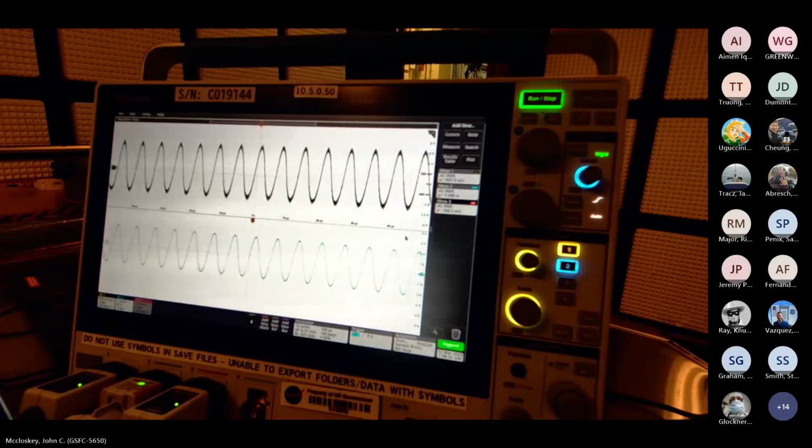If that's how your software works, and it only gives you the option to read a straight up RMS value from your scope, well, then that's what you have to do, but you have to be extra careful because AC coupling can fool you, and I'll get to that when we hook up to the unit under test. But does anybody have any questions about the pre-calibration step before I move on to the next step?